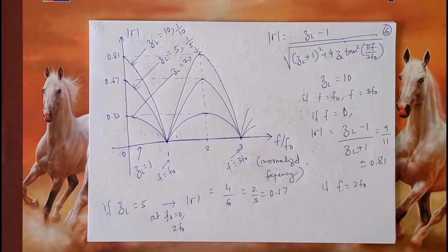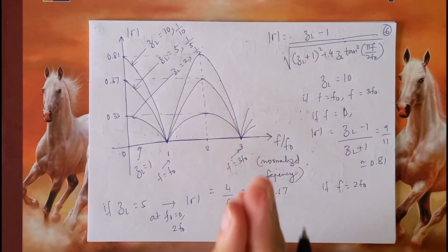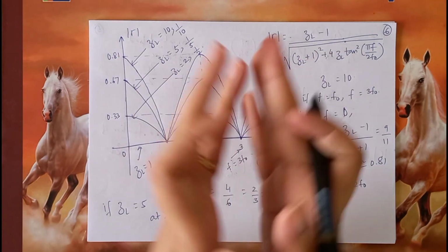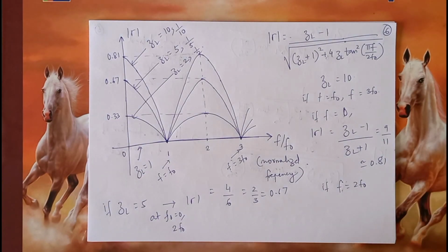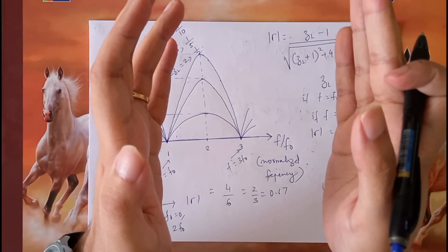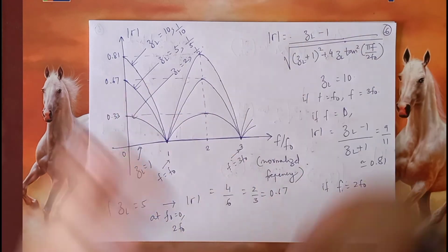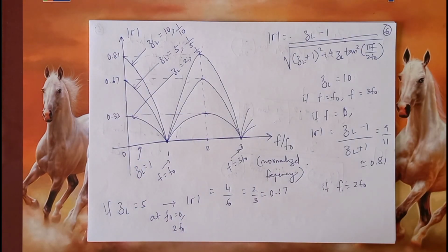So in this lecture, we essentially completed the transient or the time domain analysis of transmission lines, and we saw that no matter which approach you take, the quarter wave transformer must have impedance equal to the geometric mean of the main line impedance and the load impedance in order to minimize the reflection coefficient.